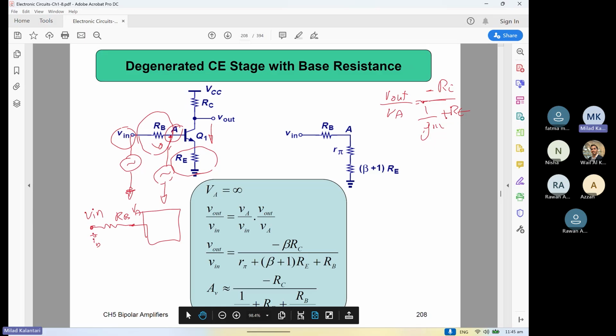Basically, you need to find the impedance. This box that you don't know has some impedance to ground, so we model this box with its input impedance first. Again, the input and output impedances are important because each box is loading some other thing.